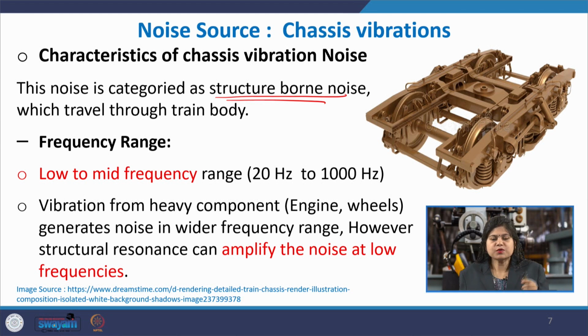Because of the dimensions that most mechanical structures have, their natural frequencies are always in the lower range. So, whenever sound passes through these structures in the form of vibrations, the lower frequencies are amplified and the higher frequencies are not.